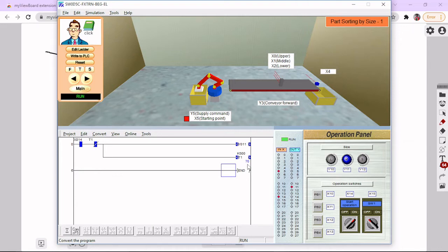So once it gets to 5 seconds, we can see that one went off and went on again. So it was at that time this T1 went to change of state, so it goes to de-energize and Y11 will go off. But because X14 is a switch and it stays energized, that's why the lamp came back on.